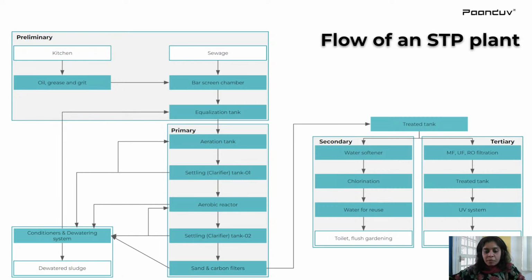In secondary treatment, there are some offensive ions such as calcium ion, magnesium ion, iron. These ions are removed, which act as the inhibitors for further processing of water. So these need to be removed efficiently. So first water is softened, then it is sent for the chlorination.